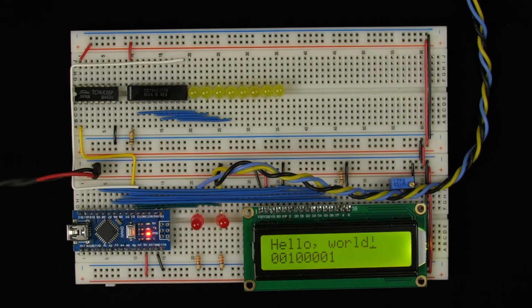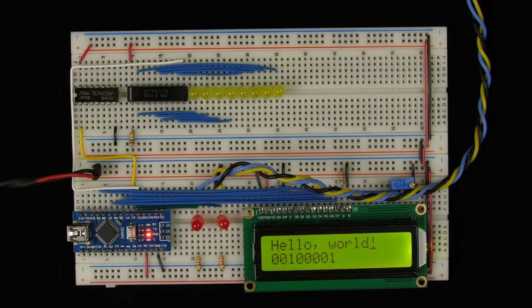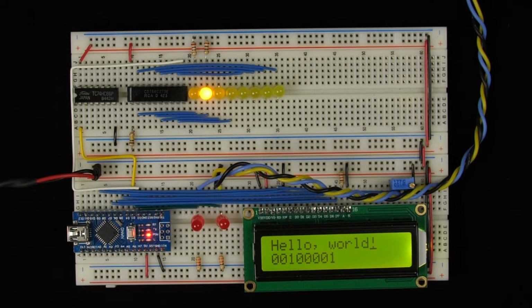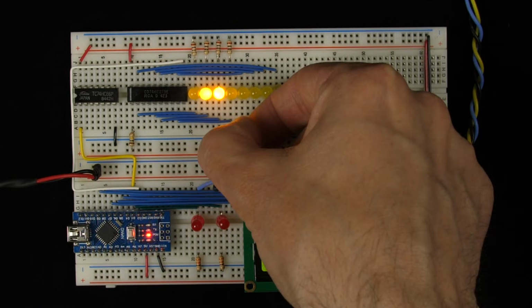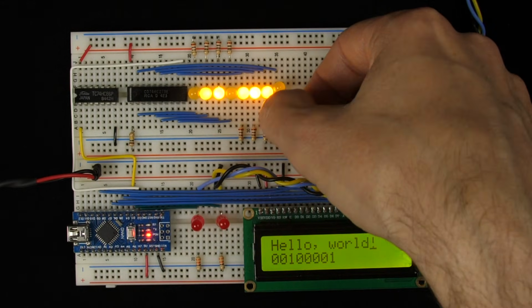And so by hooking an LED up to each one, we'll be able to see whether it's storing a 0 or a 1. Then I'm going to connect the other side of each of these LEDs to ground through a current limiting resistor. I think this is just a 270 ohm resistor, something like that. And as I'm hooking this up, it looks like some of these bits are on, but I would expect just sort of random data in the D flip-flop.